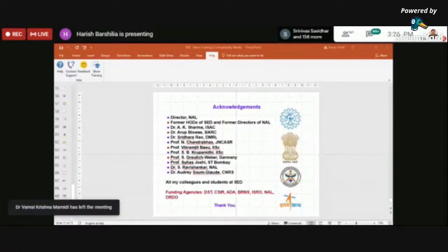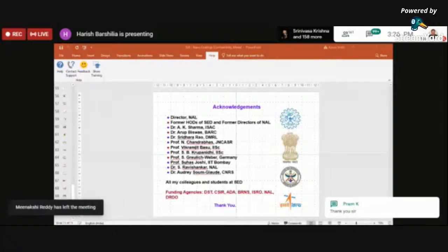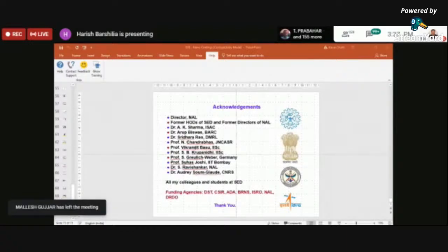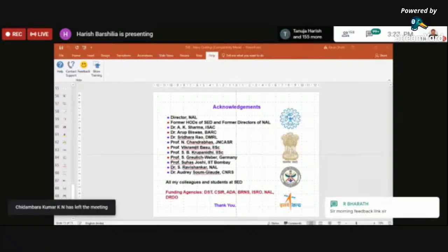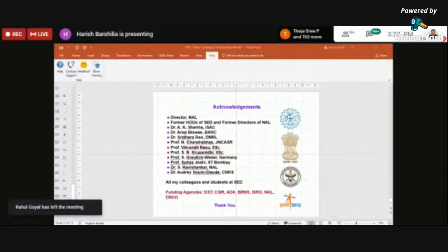No, we cannot use it. It's a very unstable material. For TBC, the basic principle which I mentioned was that we are talking about a temperature of about say 1200 to 2000 degrees Celsius. Unfortunately, this molybdenum disulfide is not even stable up to say 500 degrees Celsius. That cannot be used. You need mostly the oxides such as zirconium oxide or yttria stabilized zirconia or aluminum oxide, and some sort of doping with rare earth material, which improves their oxidation properties.